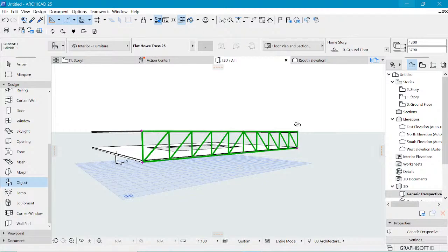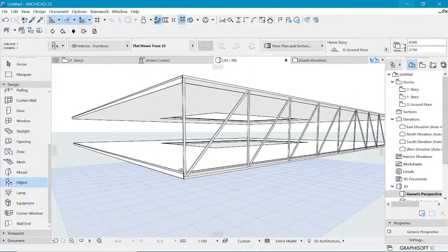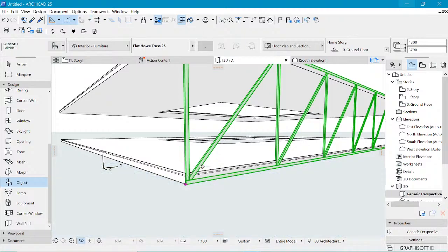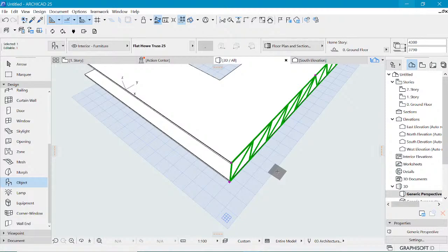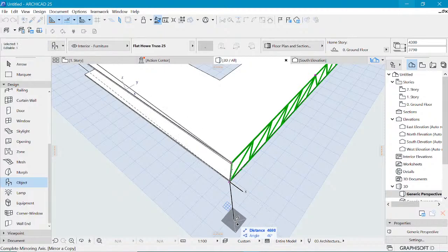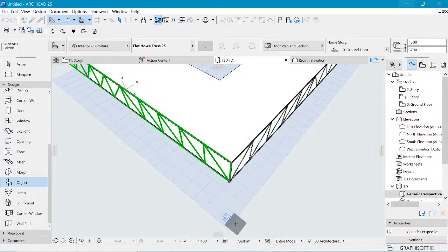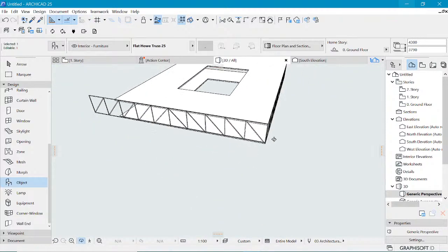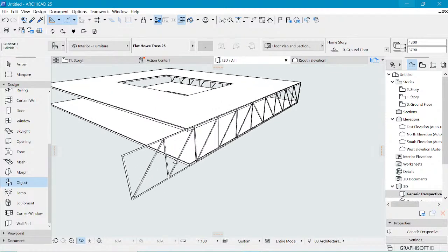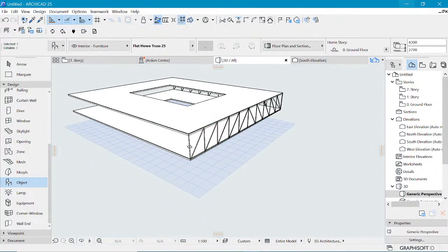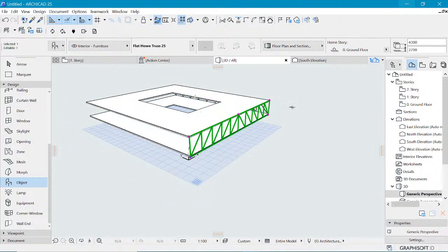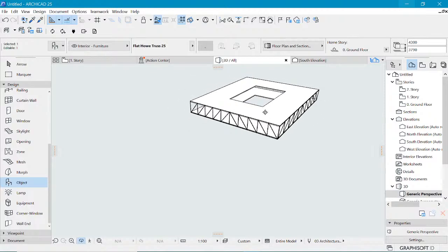So let's duplicate the same thing on either side. Here in 3D, how do we duplicate? We just need to mirror. We can mirror this with Control Shift M, in order to mirror along this axis here, 45 degrees, right? When we mirror, you can see that now we have this here, and we can move this backward to somewhere like there. And we also mirror those two now to get the rest of the two sides.